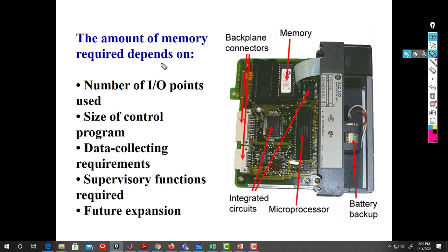So let's see what's here. The amount of memory required depends on the number of inputs and outputs. So when you select a PLC with some amount of memory, think about your number of inputs and outputs, the size of the control program, and the data collecting requirement, how much data you want to collect.